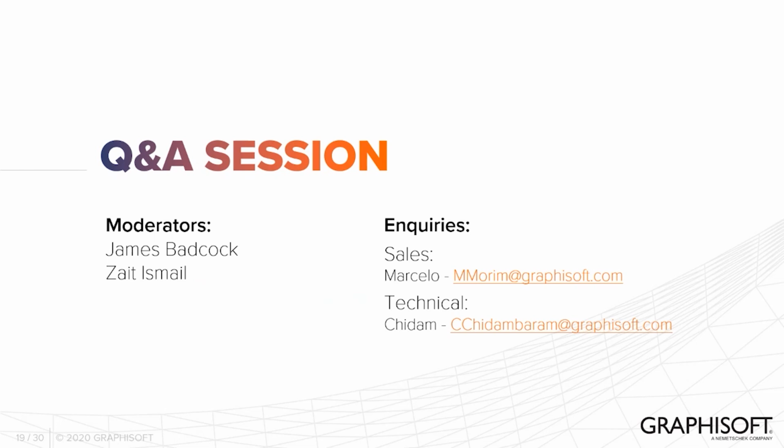The next question is just regarding the teamwork notification, if there's any prompts. Currently, if ARCHICAD is in the background, you won't necessarily get a notification that there is a new message. So you will see it when you're inside ARCHICAD. If you do enable the ARCHICAD sounds though, in the work environment, then you can hear a noise when a new message comes up. This does enable all ARCHICAD sounds though, but this is an option.